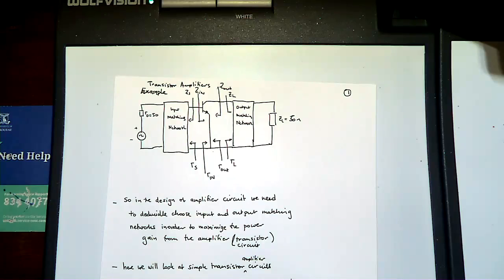Because if you look at a 741, if you go past, say, a megahertz, it doesn't provide any gain, right? Now some of the others might go up to 10 megahertz or 100 megahertz, but what I'm asking is look up and see what dictates the maximum frequency at which that operates as an amplifier. How do you define it, or how do you determine it if someone gave you a data sheet?